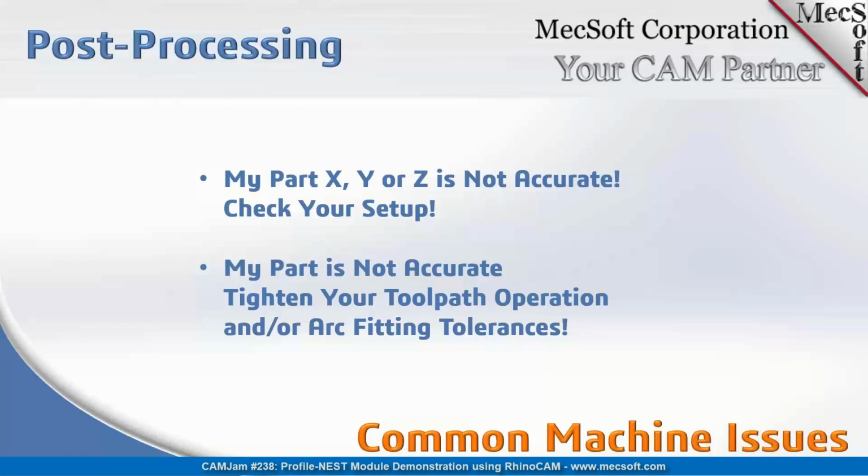There are a lot of things that could go wrong with your machine, but commonly, if you're not seeing the correct accuracy that you think you should be seeing, we're not talking about thousandths of accuracy shifting one way or the other. We're talking about if things are noticeably wrong, it's not the right Z height, it's not cutting in the right direction, it's not even in the right area where my stock is or something like that. Some of the things you can check is just do the checklist from your machine for checking the machine accuracy and check your setup itself.